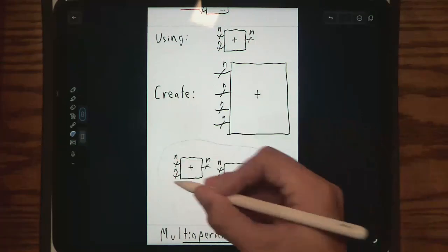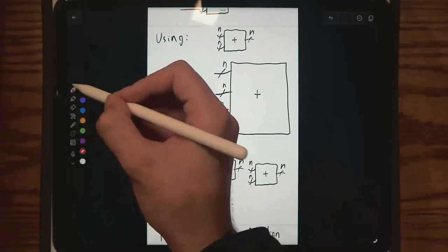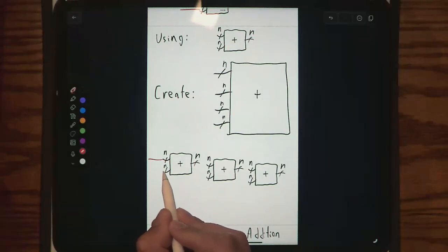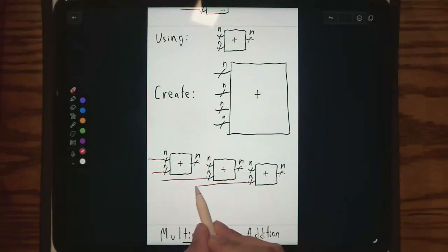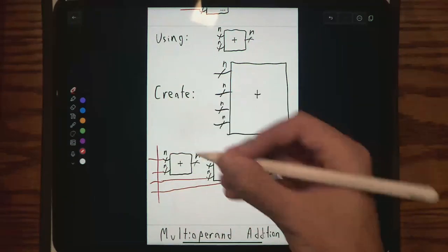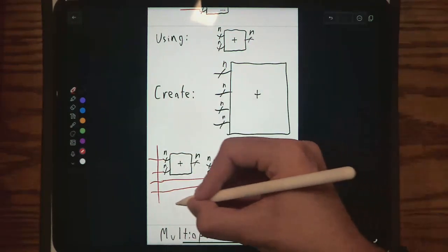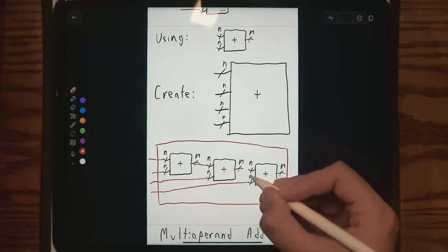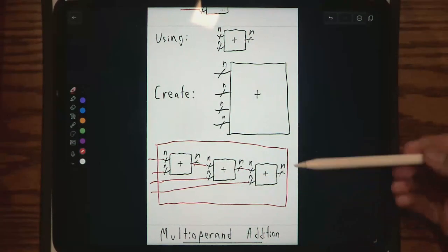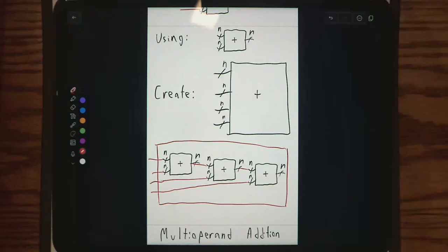Where we still have 4 additions that we can do. So we have input, and then input, and then input here. So we have 4 adders. And sometimes it may be the case that you want to implement your multi-operand adder using this structure. Maybe this is not the slowest thing in your circuit. Maybe there's something else that's slower that's taking up all the time, that is causing your clock frequency to be slower. So it doesn't matter that this specific part is running slower because something else in your circuit is the slowest part. If that makes sense.